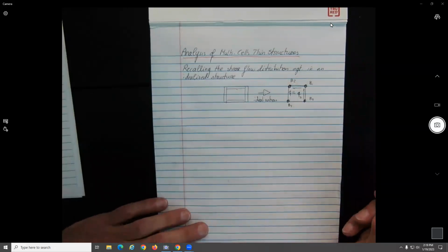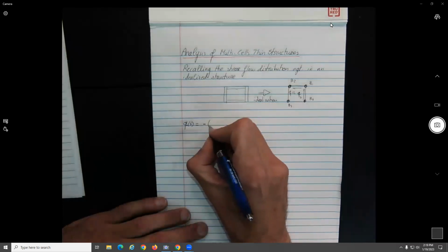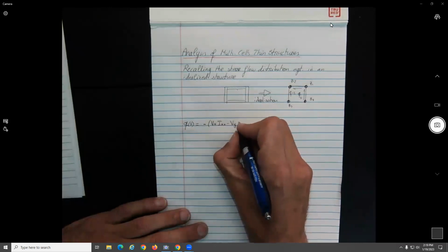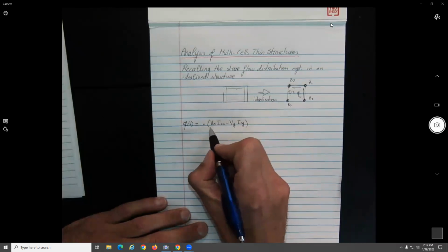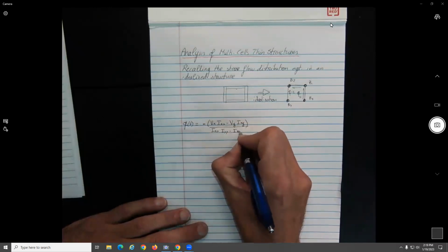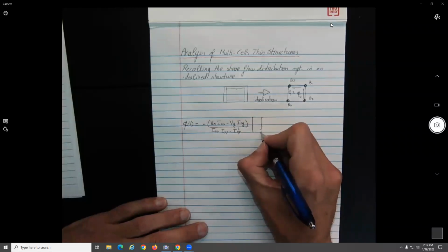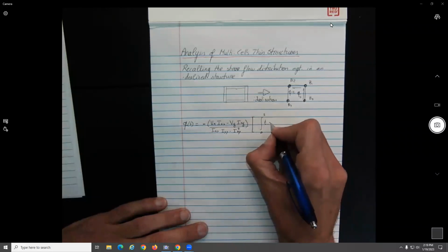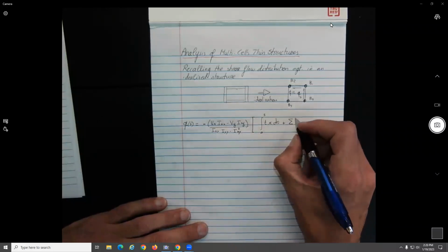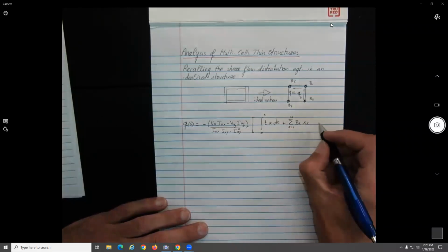So maybe you might remember or not remember that equation, but basically the equation is of the form, let's say, q of s is equal to negative, and it's quite long, this is the full equation, (Vx Ixx minus Vy Ixy) divided by (Ixx Iyy minus Ixy squared), and this is an important term over here, times the integral from 0 to s of t x ds, plus the summation r equal to 1 to n of B sub r x sub r.